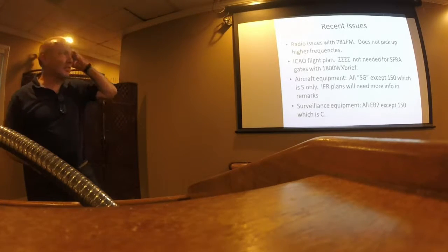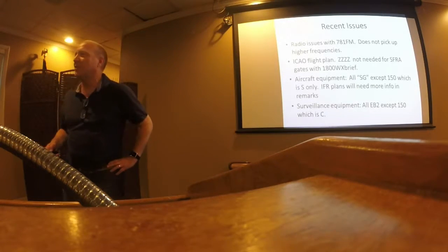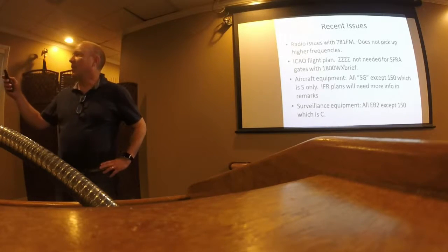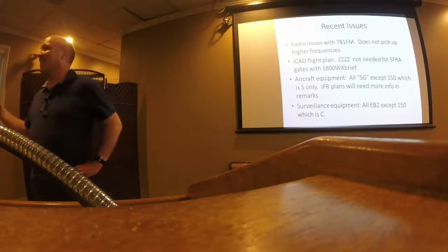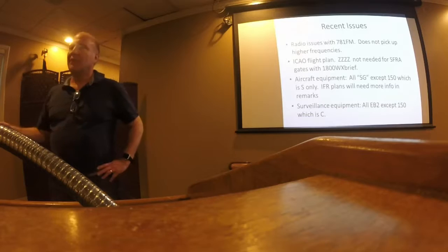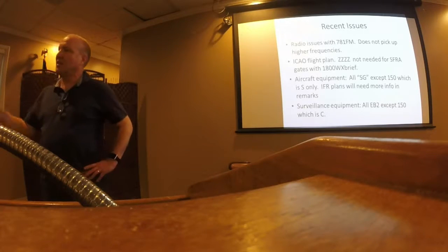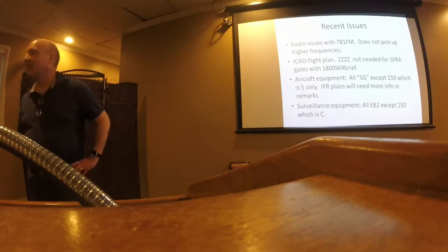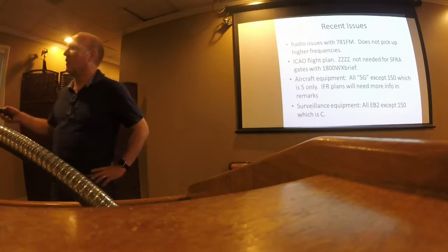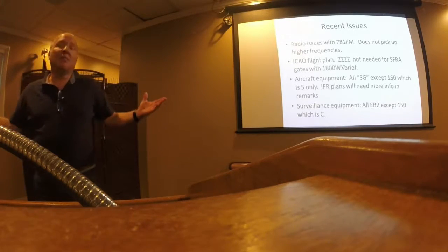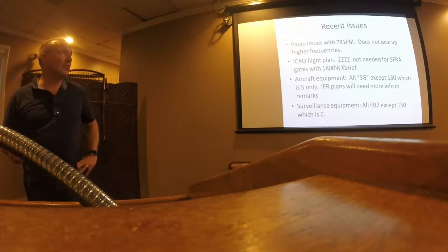Recent issues. Just to 781 Fox Mike, the radio's not picking up 132.77. We thought it was just the #1 radio. Sue and I swapped that out. It's not the radio. We think it's the antenna. If you're flying that airplane, the second one was picking up 132.77, but there was a squawk that it didn't happen the other day. So if it happens, you'll have to tell them and go back to 119.7 or a frequency that you can use. Or if it becomes a problem, we've ordered the antenna. Hopefully we get the antenna in soon, and hopefully that is the issue.